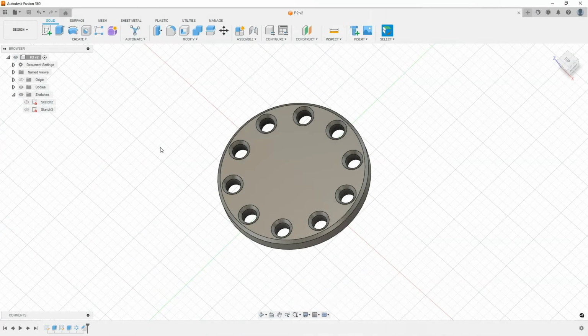Previously, we discussed the circular pattern, and I mentioned the second type of pattern, the rectangular pattern. This type of pattern is also worth getting to know at the initial stage of learning Fusion 360, and when it comes to a rectangular pattern, similarly to a circular pattern, we can easily get additional copies of the selected feature, but in this case arranged along a line and in a direction perpendicular to this line. It will be an arrangement of features in the shape of a rectangle.